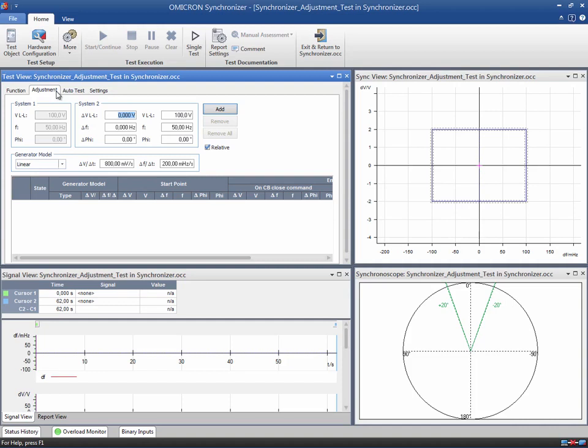During the controlling process, all points are driven to a specific target point inside the synchronizing window. This target point depends on the logic and configuration of the relay, in this case, 40 MHz and 0 volts. However, keep in mind that the relay will issue the close command as soon as all the conditions are met, whether the target point has been reached or not. The module will check that the time elapsed between the start signal and the CB close command is within the maximum synchronization time.